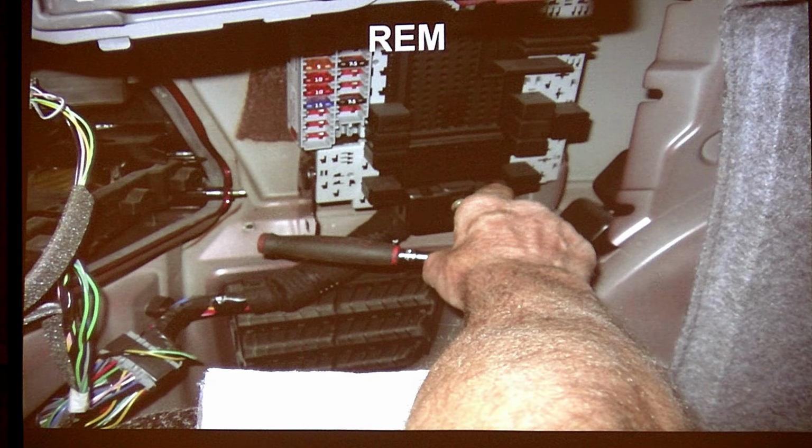What if the termination resistor is inside one of the other modules, the suspected module that I'm going to disconnect? I take a 120 ohm resistor from my decade box. I have them back there, you can look at them. I use decade boxes all the time.